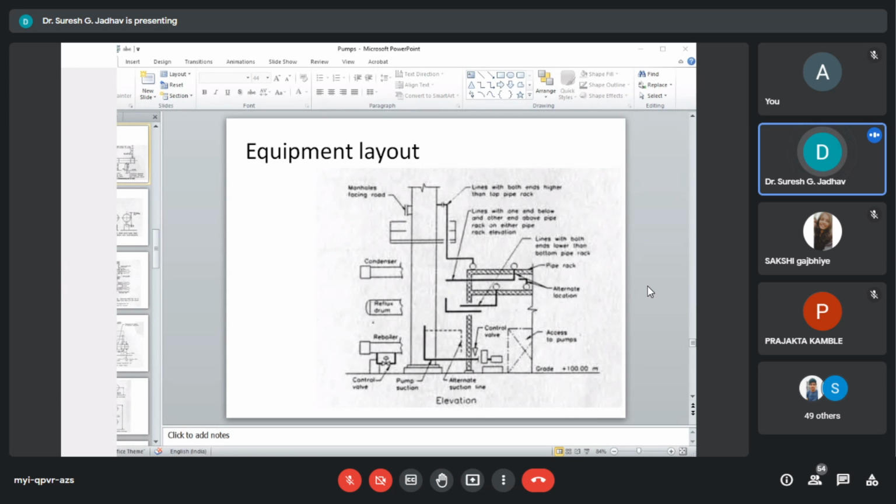The details of support on the skirt or on adjacent structure are worked out considering the temperature of operations. Some reboilers have a condensate or liquid holding pot located after the tube side outlet, as shown in these elevations. When high capacity steam traps are provided, the top of the condensate pot should not be higher than the bottom of the exchanger shell to avoid flooding of the tubes with condensate, adversely affecting the performance of the exchanger.